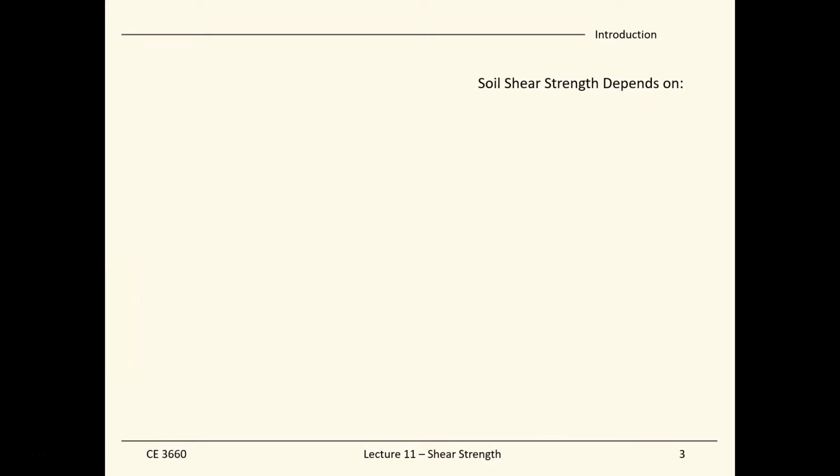If we go back to the civil engineering case history library, you see many of them are about foundation failure, which is the case where the soil strength cannot handle the structural load. So it's not a structural problem, but a geotechnical engineering problem that highly relies on the characterization of the soil strength.